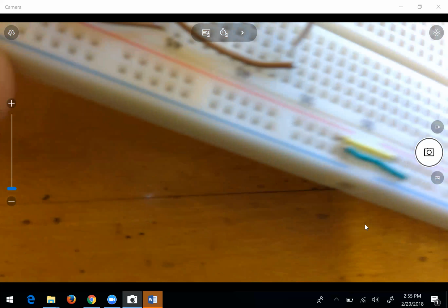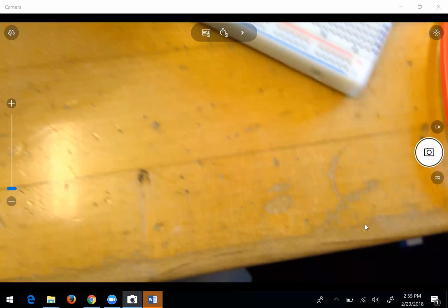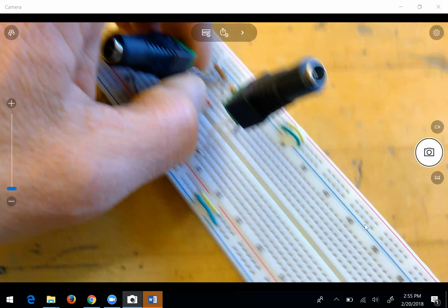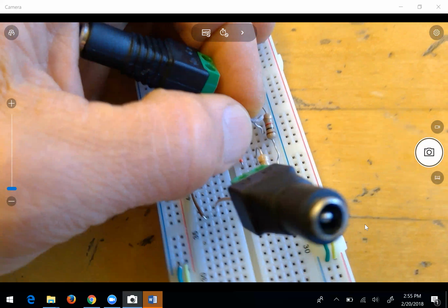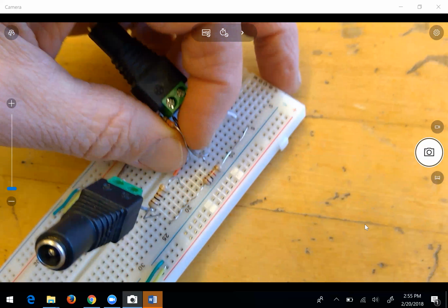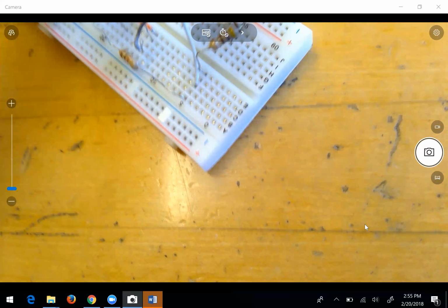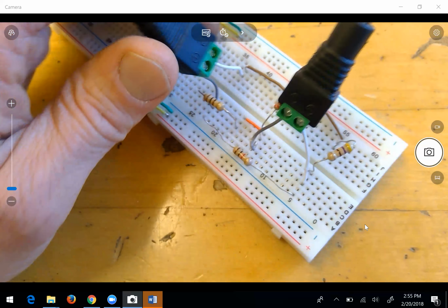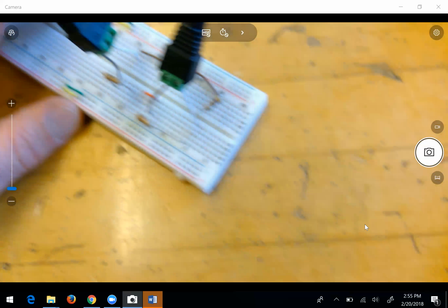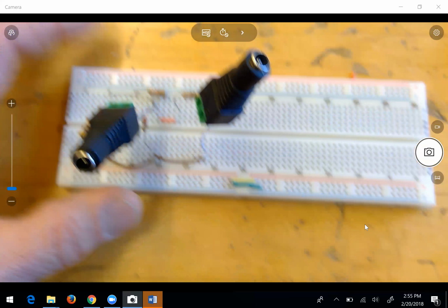You might want to try straightening out that wire. It's kind of curly-cued at the end there. You might not be getting a good connection if it's not going in all the way. That wire should be straight if possible. When you have those weird bends in it, you're taking away some of the wire that can go into the clip, so that might give you a weak or improper connection. You have these pliers here, which you can use to straighten it out. That's a good skill to get used to.